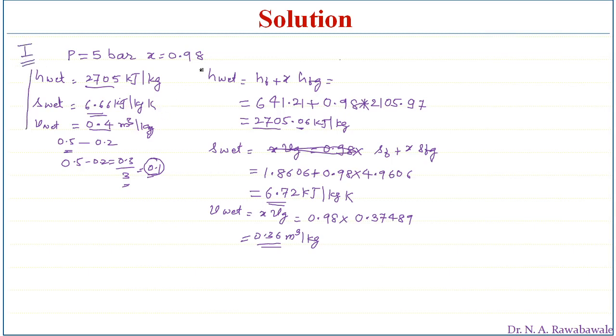In the second method we use the steam table and remember the formulas, and by using the formulas we can find the enthalpy, entropy and specific volume of steam. If at least two properties are known, such as pressure and dryness fraction, or pressure and temperature of superheated steam, or pressure and enthalpy, the rest of the properties can be obtained using the Mollier chart.